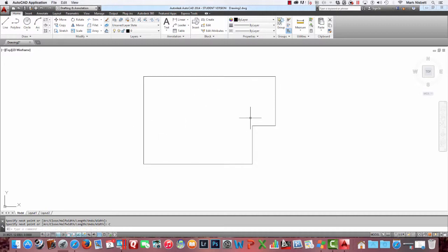This is now a polyline. So when I want to offset this, it's very easy to use the offset command and give it an offset distance of 6.5 inches or whatever the wall thickness might be. So I can do that sort of thing, and I immediately have walls. That's a very big time saver over offsetting individual lines.